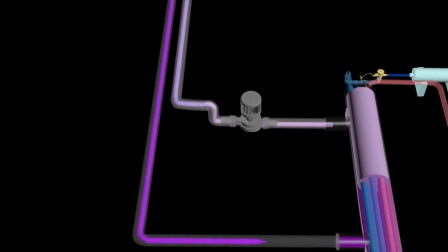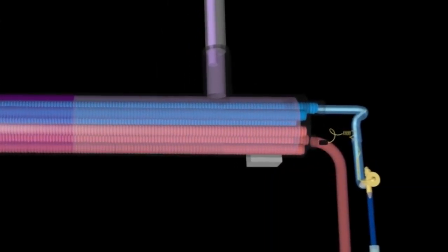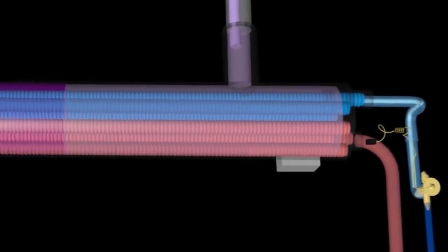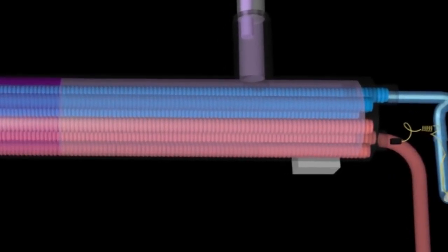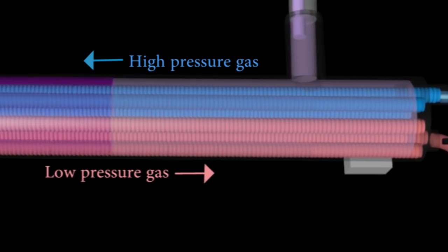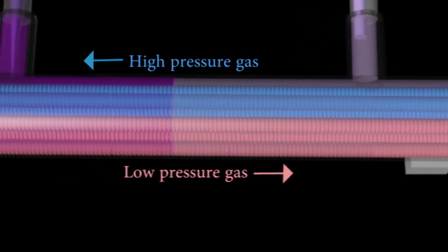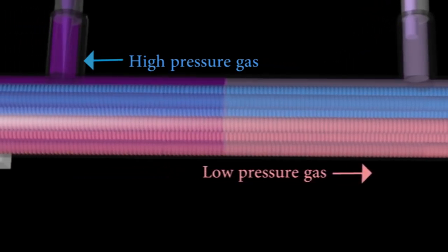When the liquid refrigerant with low temperature and pressure absorbs heat from the chilled water, the refrigerant will evaporate to low-pressure gas. The evaporator most commonly used is the shell and tube type, where the refrigerant flows in the tube and the water floods the shell.